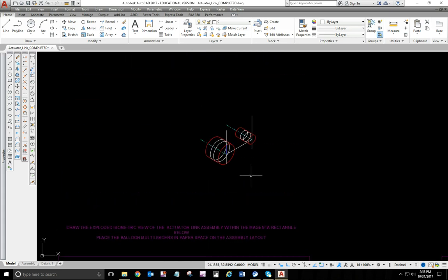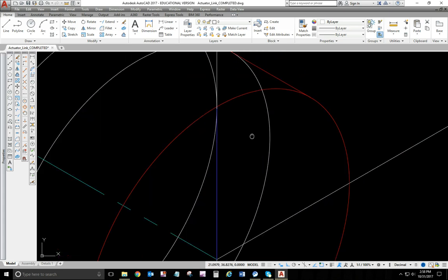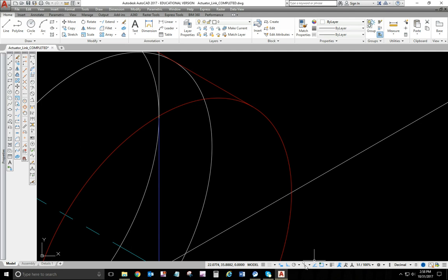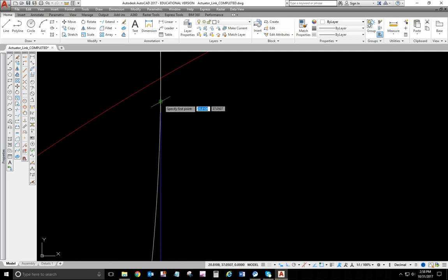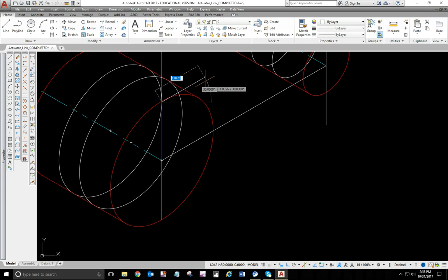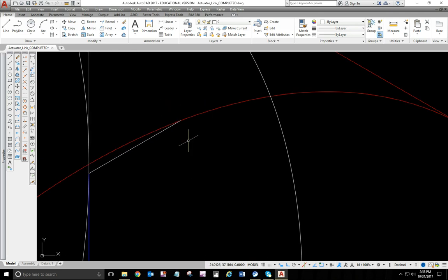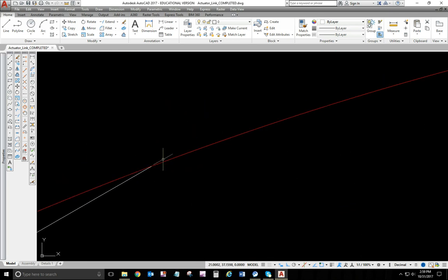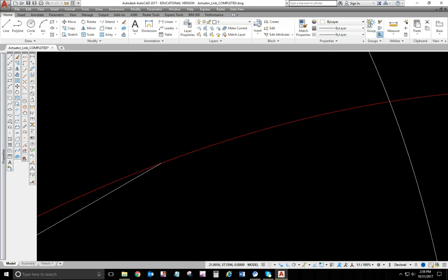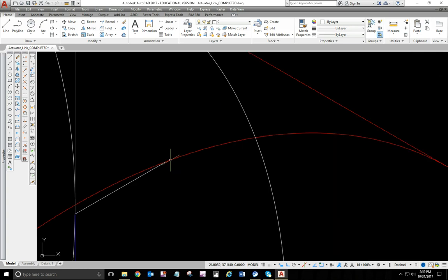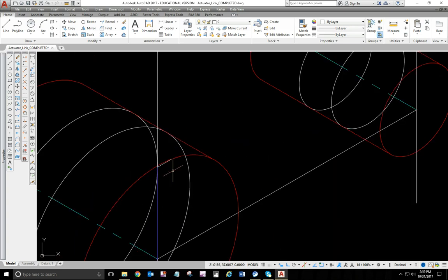So now I come back to here. Let's go back into ISO mode. I want to go line from the endpoint of the one I copied over out isometrically, 0.2148. And you look, it intersects my ISO ellipse. That is the point of tangency. Okay.